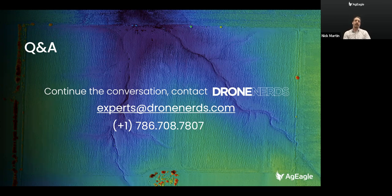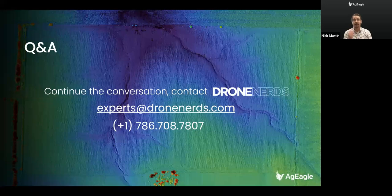So put the image in your mind of flying a fixed wing drone at 10 feet altitude. It's going to be flying much too fast, so essentially you have the same effect of slowing down by going higher. You can overspeed the camera, but you don't want to. And 2 captures a second is pretty good. That's going to allow a wide variety of speeds and altitudes.